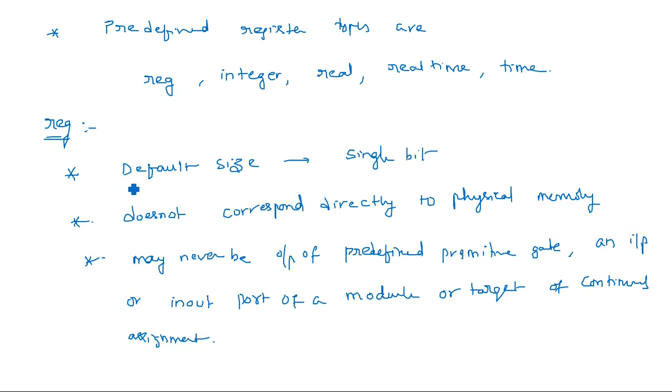And coming to the second type, integer. Integer supports numeric computation in procedural statements. It is for numeric values. It is represented internally to the word length of the host machine, about 32 bits. So it has 32 bits of information. Initially it starts from 0 and it is having a fixed word size of 32 bits.